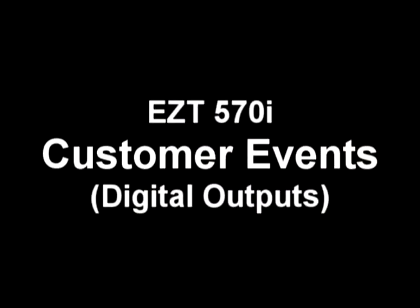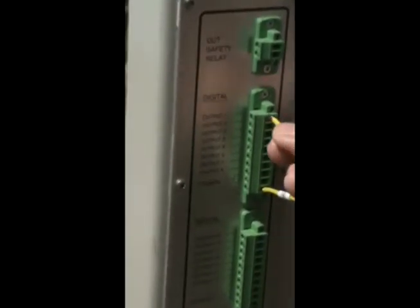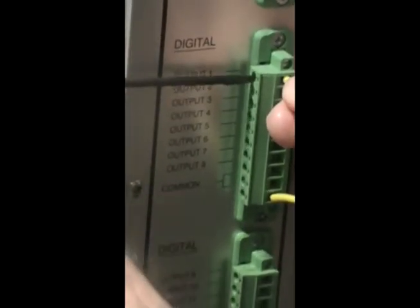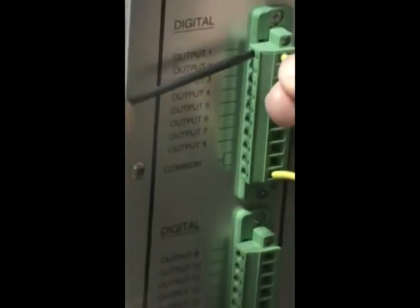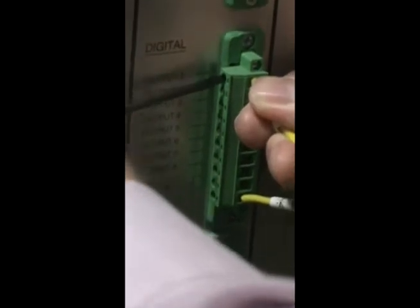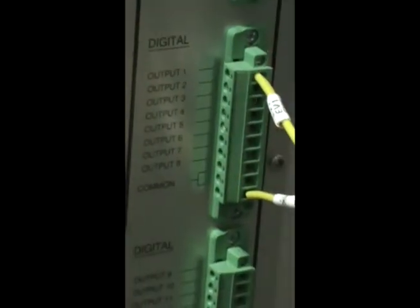The EZT570i digital output option provides 15 digital outputs which can be used as event outputs, alarm outputs, or for other signaling needs. These outputs can be turned on or off in response to several types of conditions. These conditions include activating the output when a profile is running, when a profile is on hold, during an alarm condition, or between step changes within a profile. The digital outputs can also be directly controlled by the optional digital inputs.